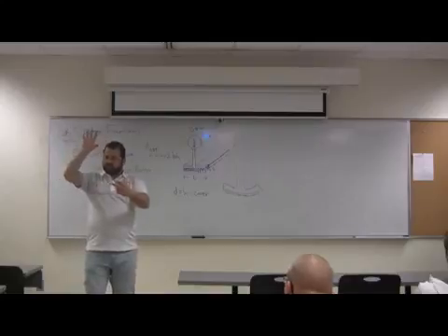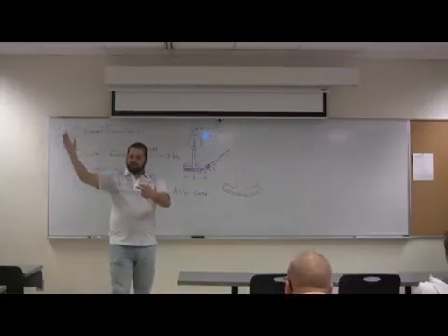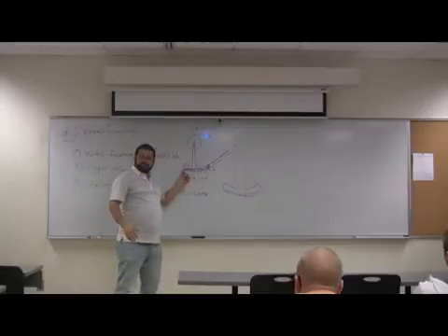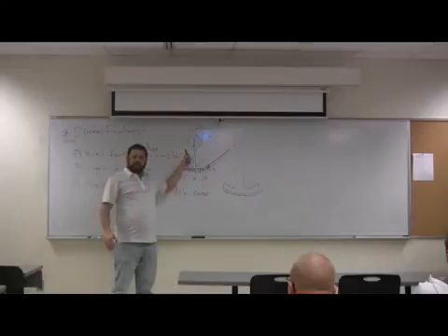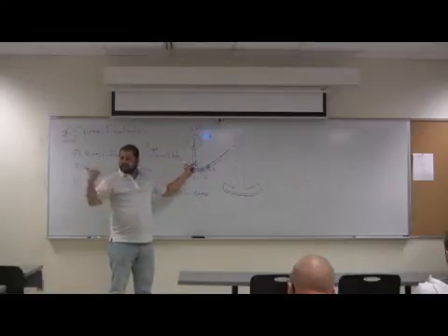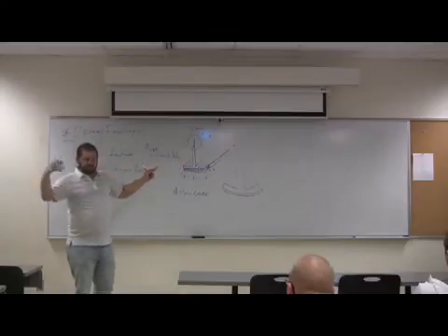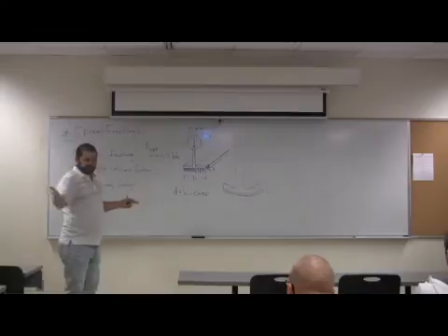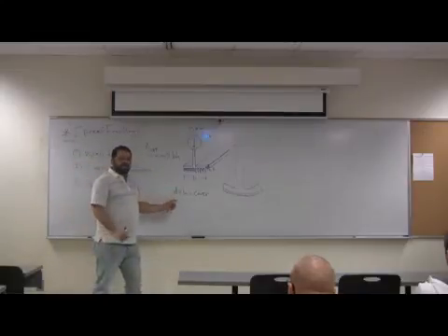The first one depends on f'c. As you increase f'c, it becomes the controlling minimum reinforcement. So when you calculate rho from the bending for this steel, you check that against rho minimum, as I said, 0.0033 or 3 square root of f'c over fy. Good? Okay.